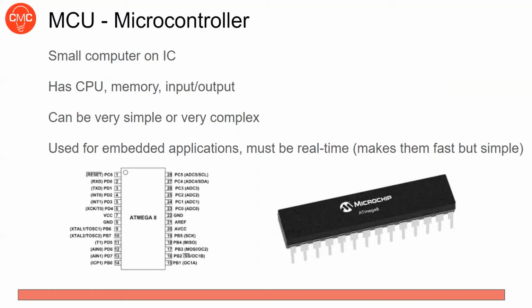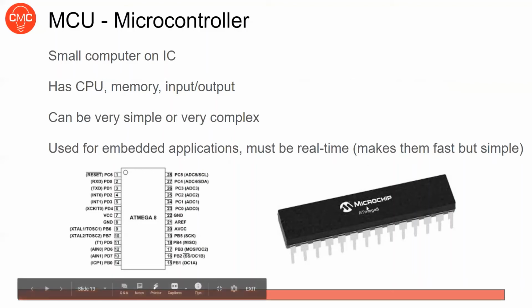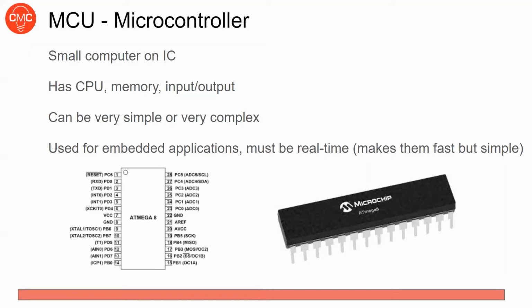The microcontroller that's used on an Arduino Uno is the Atmega 328P. It's the part number for it. This is a smaller Atmega, which we'll be using for the first project in this course because it's very simple, easy to use, well documented, and you can program it with an Arduino IDE if you don't like programming like me.